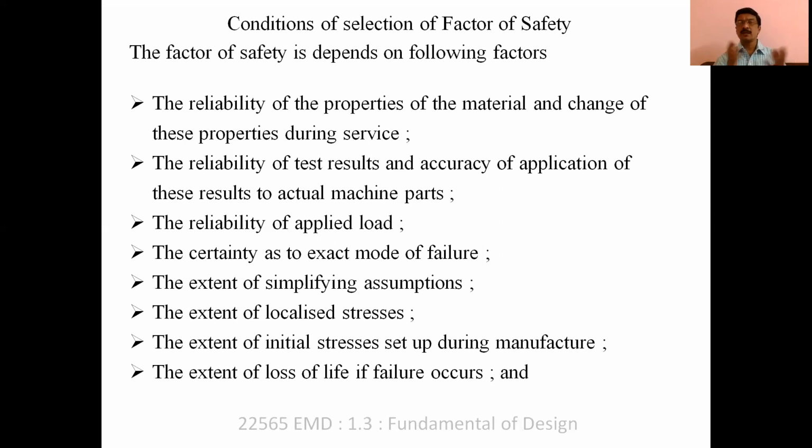Just like if you take an example of a steel rope used for a lift, if there is a sudden breakage, the complete lift may fall down, and because of that there is a loss of life. Or if you think about a bridge structure and the ropes used for bridges, the failure directly causes loss of life. So in that case, you should not take risk. You should go for higher and higher factor of safety.